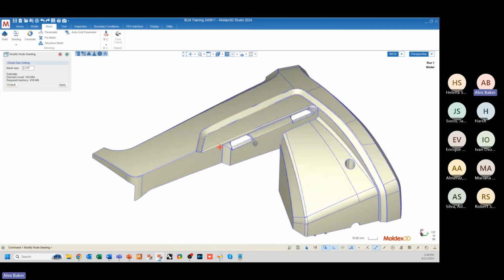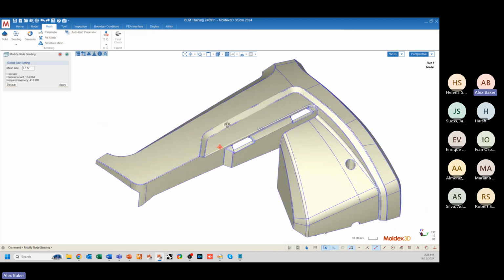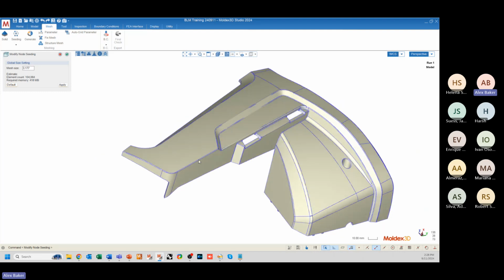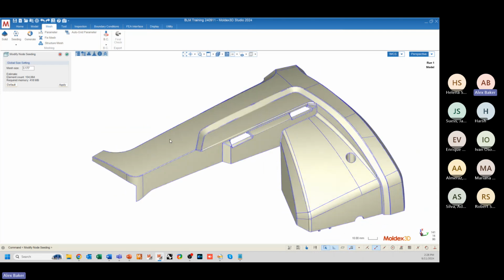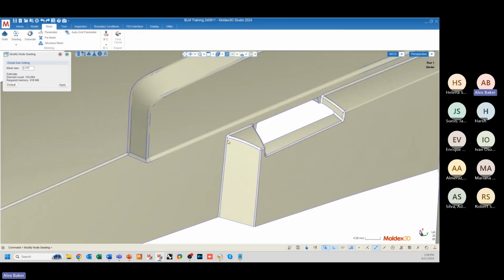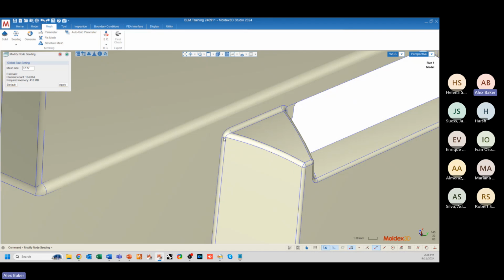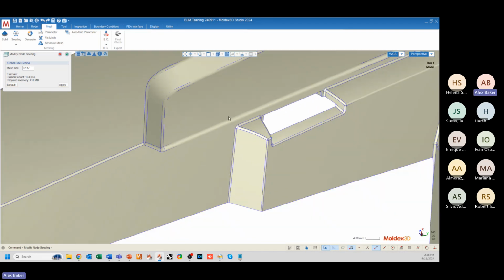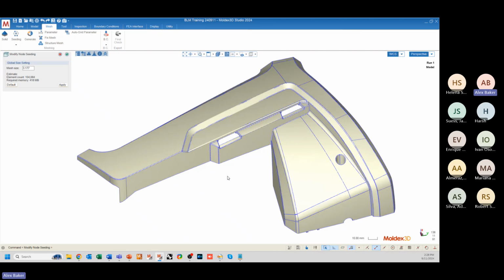For any sort of complex geometry like this, or even a little bit more complicated than this, default node seeding is very, very good. But just know that if you have a simple geometry, it's kind of counterintuitive actually. If you have a more simple geometry, the default is a little bit less accurate. The reason for that is just because there's less of a diverse array of feature line lengths. And if that's the case, then it can't really determine a good node seeding. Like if I just had a box that really only has 12 feature lines across the geometry, 4 on the top, 4 on the bottom, and then 4 on the side, it can't really define a good node seeding for a simple geometry.